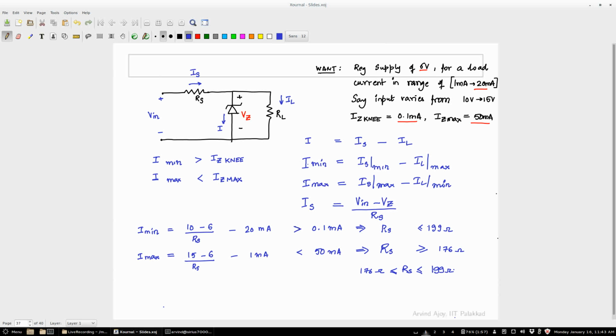They don't give you all values. It's actually in kind of a logarithmic range. Okay. So 3.3, they'll give you 2.2, there's a 2, there's a 1.8, 1.5, right? There's a 1. But 0.3 is not available, right? So you want a resistance which is easily available. And 180 ohms is an easily available resistance that you can choose. Okay. So 180 sets the value of RS.